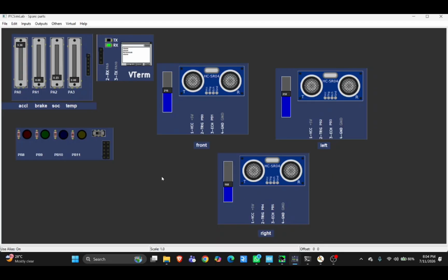Here I have used the STM32 F103C8T6 Blue Pill microcontroller, programmed using embedded C in STM32CubeIDE. A Python based GUI runs locally, using matplotlib to visualize live data. A bridge, a virtual bidirectional UART port, operates at a baud rate of 115200.